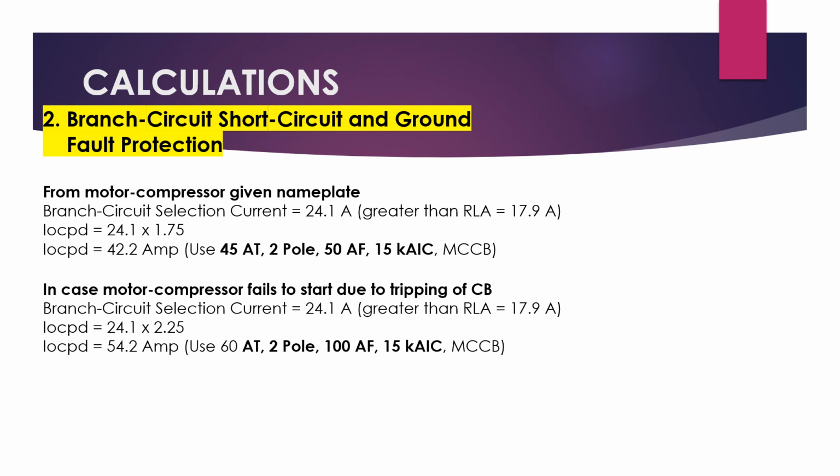From the table, in my previous videos also, you will see that you have to use 45 ampere trip, 2 pole, 50 ampere frame, and 15 kAIC or 15 kiloampere interrupting capacity.